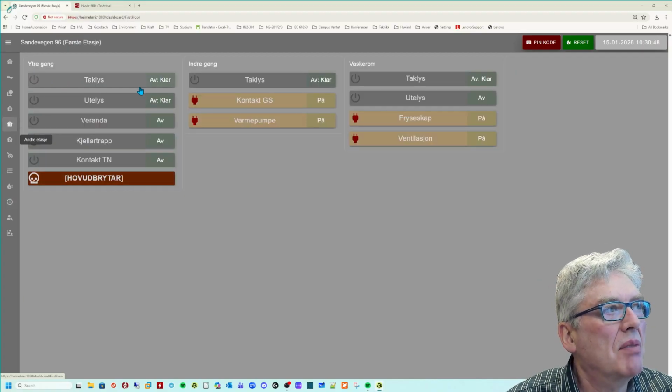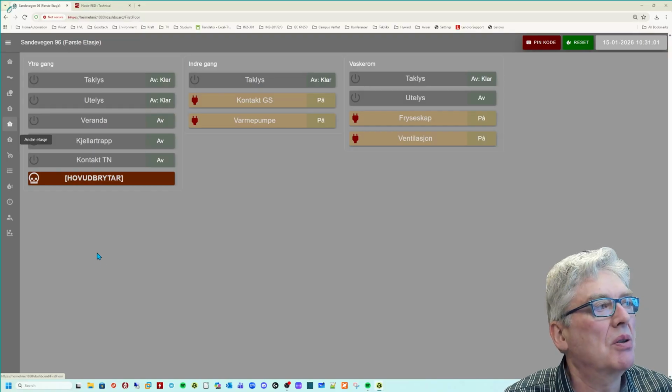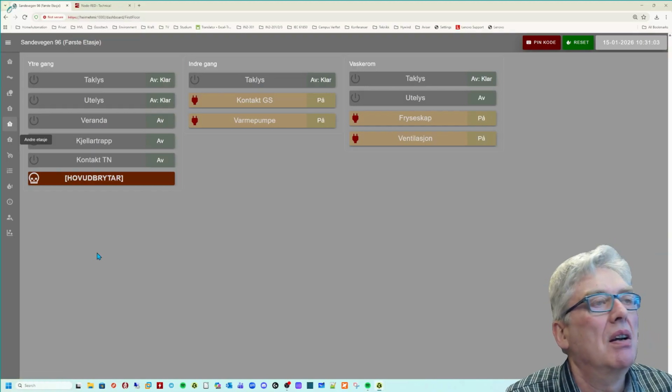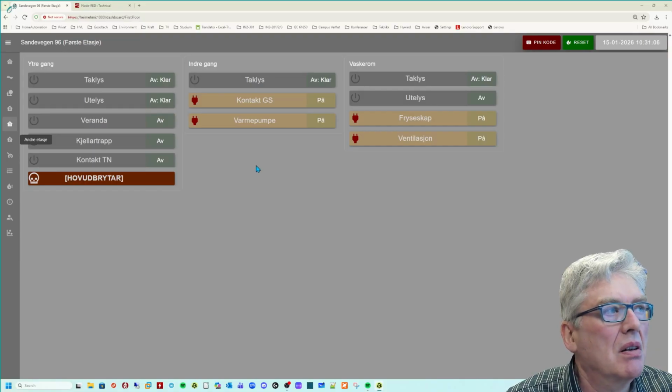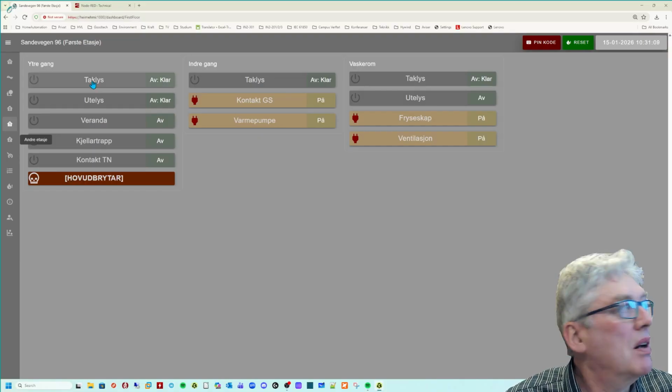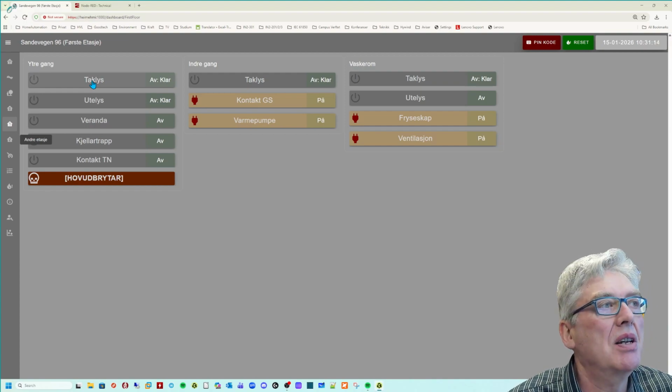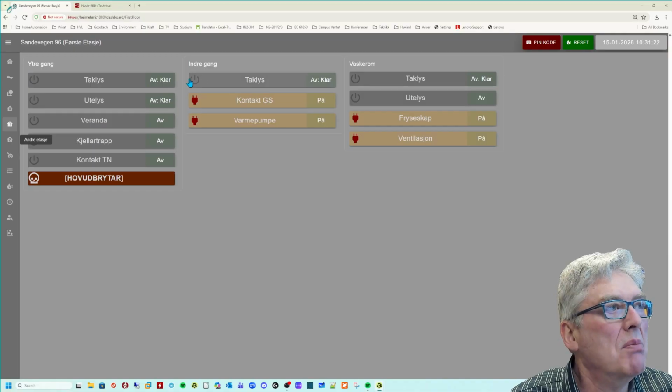These are my outer entrance, the roof lighting. And here was one. This is of course a progress bar too. Vuetify, and this is the button. But then just this center icon on the left, I couldn't figure out how to do it with the FlowFuse stuff. So basically you have to script it. So ready here means that if it's not that dark outside, but it's dark, so I need a light on inside. So when I move into my outer entrance, the light is switched on, and then it's switched on for an amount of time, and then it's just counting down here and going back to ready.